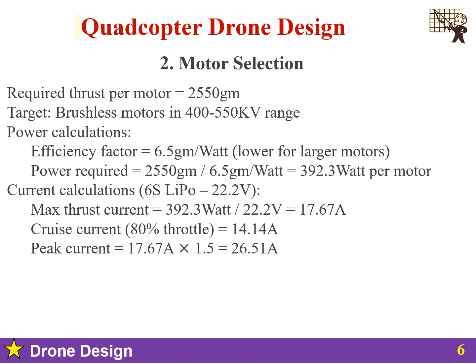Why ultra low kV would be a question. Lower kV motors provide higher torque at lower RPM, essential for turning the massive 16 to 18-inch propellers required for efficient thrust at this scale. Think of it like gear ratios in vehicles. Heavy trucks use lower gear ratios for maximum torque, exactly as we use lower kV motors for heavy lift applications.